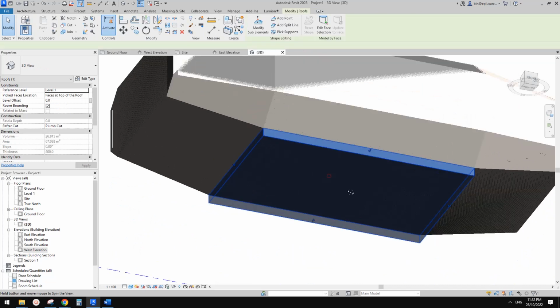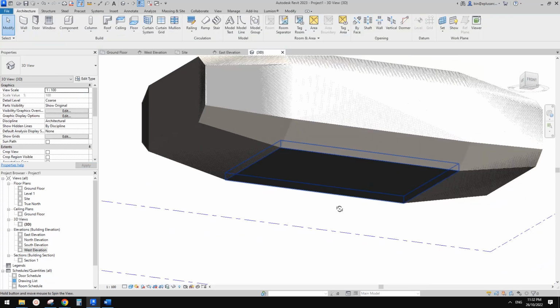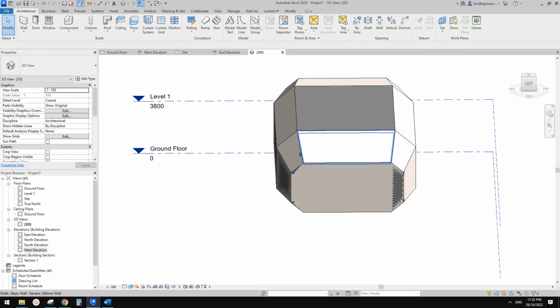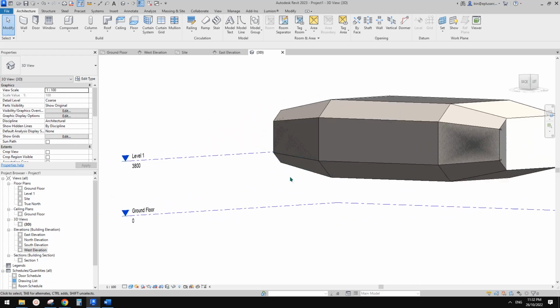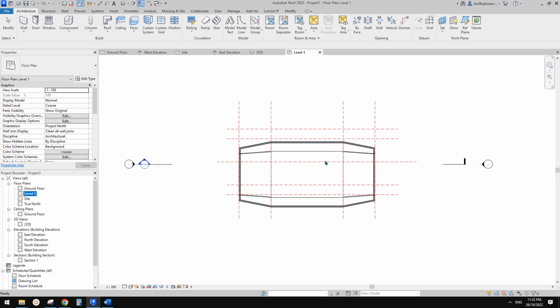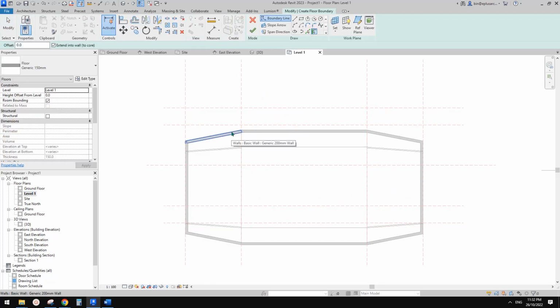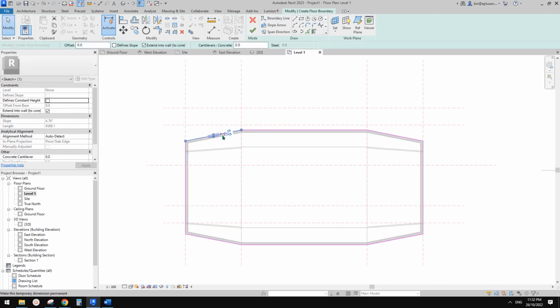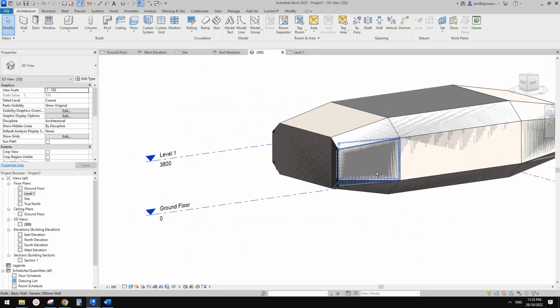And also you can see it's on the wrong side. You can also change this one to place it up. And you probably need to create a floor, so if I want to create a floor on level 1, I'll probably just go to level 1 and create a floor. I'll try to use pick wall, and maybe just flip them inside and then go to 3D view.